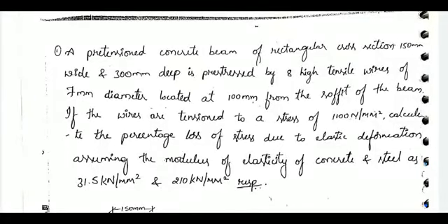Hi all. Today we are discussing the problems on calculation of losses of prestress. So in the first problem, we'll start with a pre-tensioned concrete beam of rectangular cross section 150 mm wide and 300 mm deep, pre-stressed by 8 high tensile wires of 7 mm diameter located at 100 mm from the soffit of the beam. If the wires are tensioned to a stress of